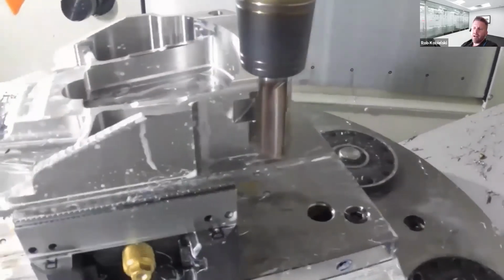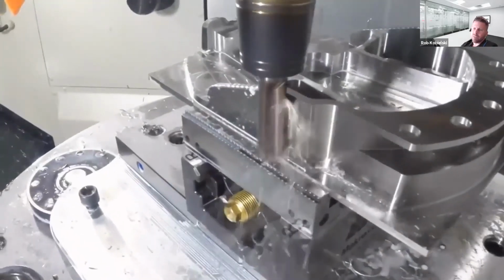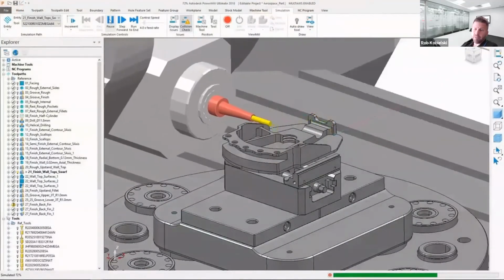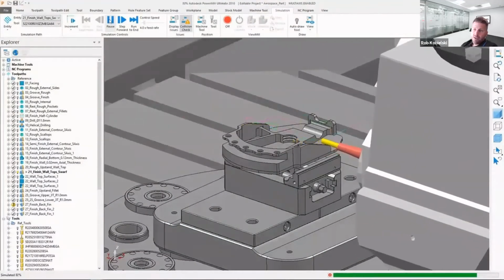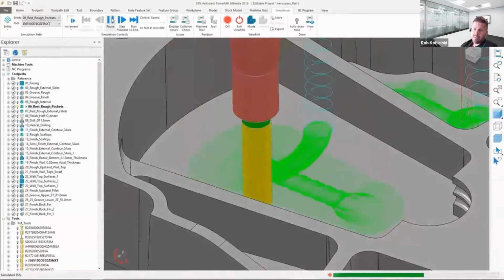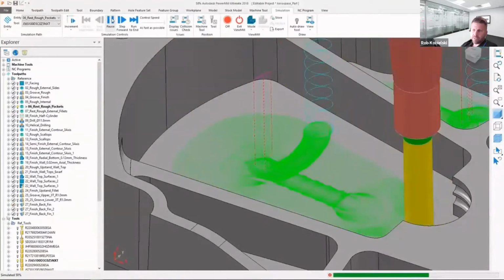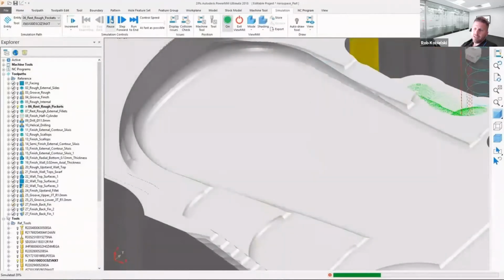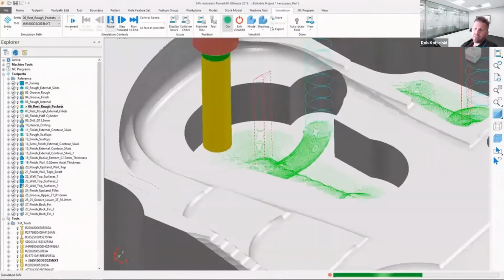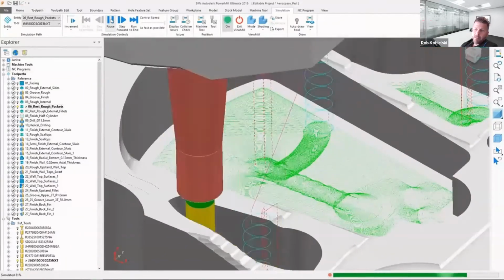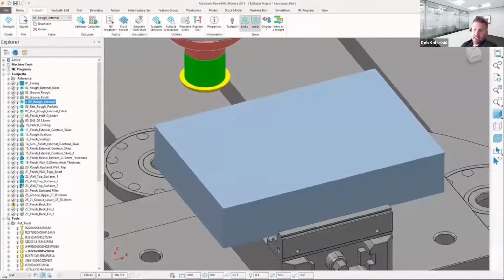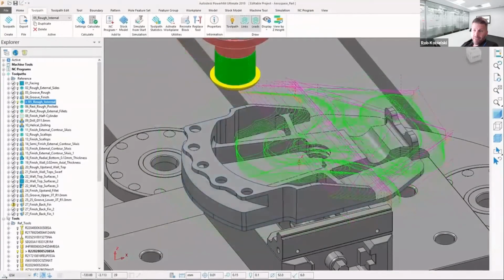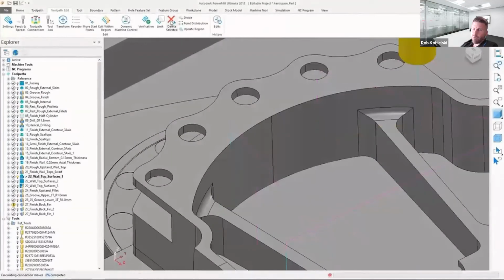Transforming part designs into reality requires a CAM package with the ability to deal with the most complex of milled parts. Fusion 360 with PowerMill has that fine level of control and flexibility required to satisfy this need. For high volume stock removal, PowerMill generates high efficiency, high-speed toolpaths such as Vortex. These decreased cycle times produce parts quicker while controlling the tool engagement to even out the load, reduce wear, and increase the life of your cutting tools. Effective stock management techniques minimize air cutting, allowing the tool to continually engage into the material. Toolpath editing can be used to quickly modify toolpaths without the need to recalculate them.